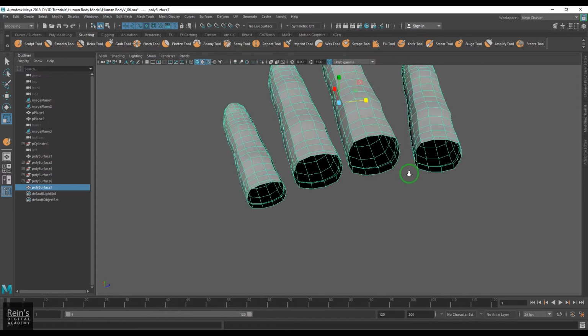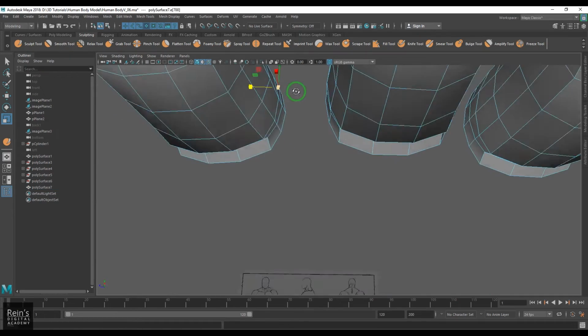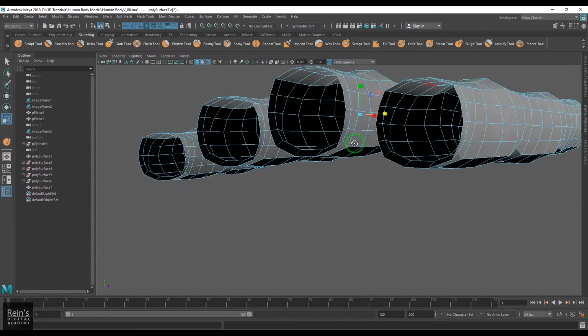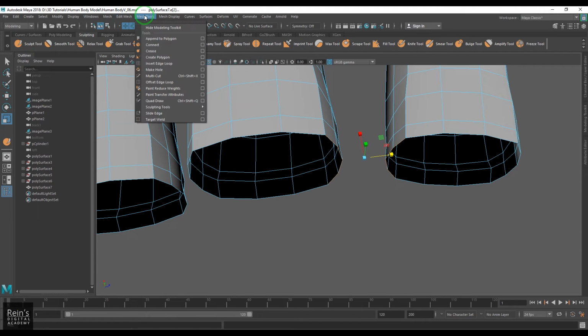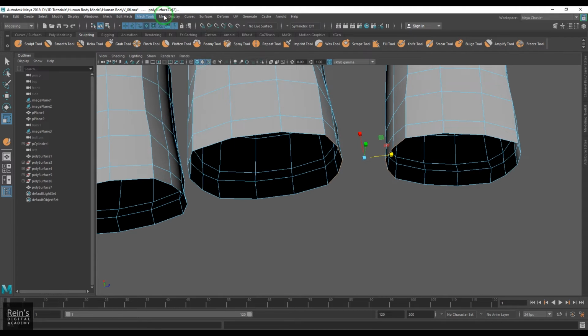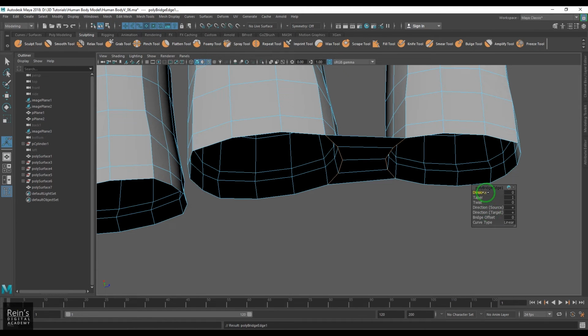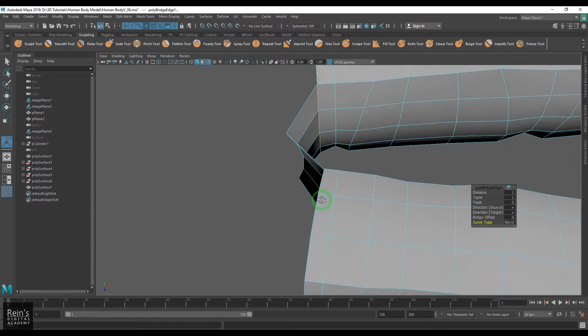Like that. So once you have got all this, what you need to do is just use the combine tool and then make it in one piece, and then start selecting these lines here. Make sure that you are selecting that many lines on both sides, and I'm going to apply this tool called bridge. So you should find it in the edit mesh and apply bridge there, and add divisions, and also make it curve or blend, and then you should be able to get that nice subdivision.